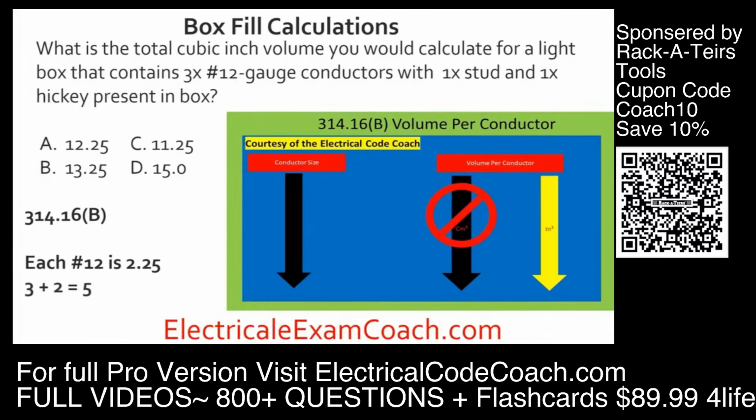We know that we have the 3 number 12s originally, but now we have to deal with the studs and the hickeys. Our code states that for each stud and each hickey, they count as 1 each based off the largest conductor that's in the box. In this case, we only have number 12s, so they're going to be grouped with the 12s. So that lets us know that we have a total of 5 number 12s. That's what I meant by we're converting everything back to conductors, and then we can do our multiplication. We take those 5 number 12s, multiply it by the cubic inch volume for 12, and we end up with 11.25 cubic inches, and we would select C.